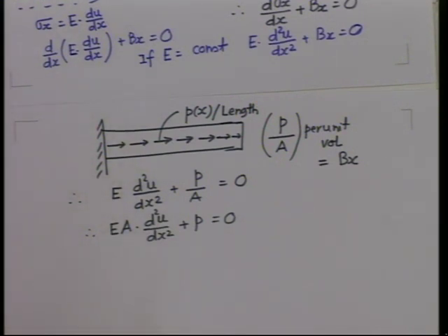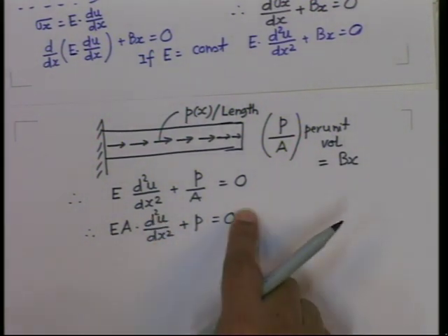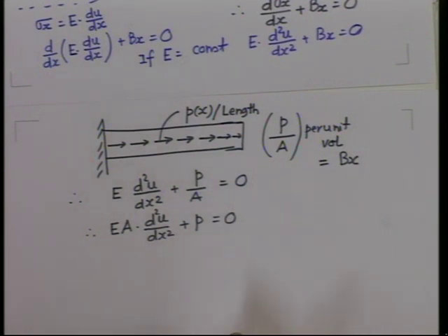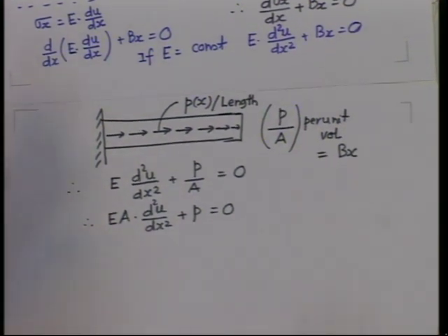It looks similar to your flexure formula, except that this is second order, flexure is fourth order, and it is P by E I instead of E A. And P is the transverse load there, not axial load, in a beam, because you want bending, flexure. So, this is your governing equation.